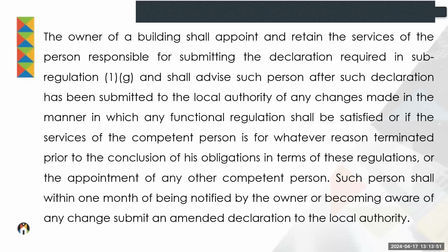However, in terms of the National Building Regulations and Standards Act, our duties as a designer do not end with the submission and the approval of the building plan. There are certain aspects where our services are still required by the owner, especially if they want to change certain things before it's erected on site. Our name is on that Form 1, and we are the only person then that can do such changes or alter the declaration that we have done.